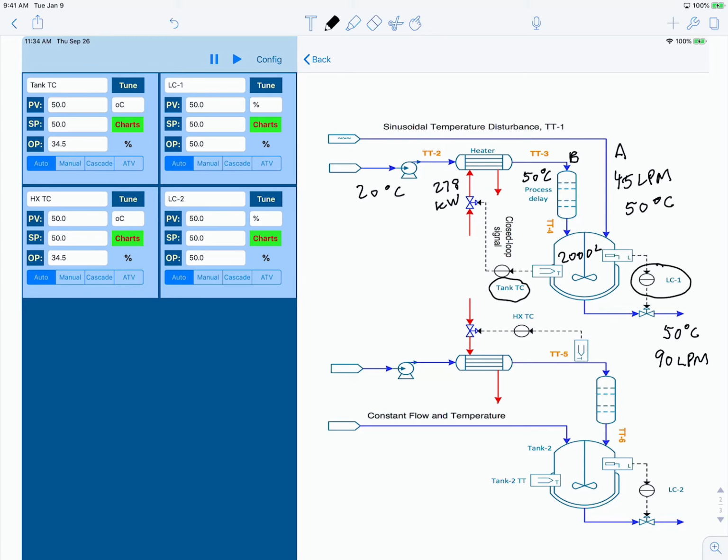It adjusts the outflow from the tank. The liquid volume and the ion exchange columns are, of course, necessary in this particular process, but they provide dynamic elements to the process, and we really don't need them to do a steady-state calculation. So let's focus on just the streams themselves and how they mix and come up with the exit temperature.